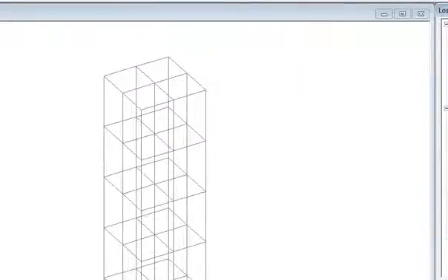Now we have already created the various load case details. The next step in the wind definition is different from the other two, the dead load and live load: go and create the wind definitions. That is, we are defining the way in which the wind will be acting, because the wind acts in various ways in various parts. Say in a coastal region the wind intensity is a little bit higher, and the safety feature is a little bit different. You can always refer to IS 875 Part 3 for the wind load definitions.